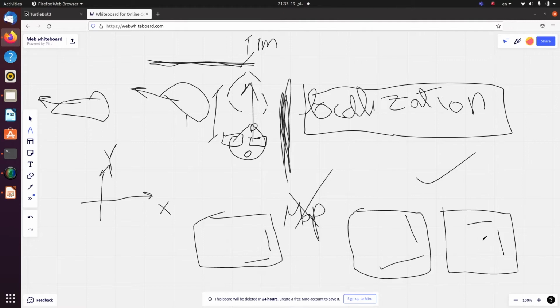So I know that the robot here was looking that way, and I know that here the robot was looking somewhere like this, a little bit rotated, and here the robot was looking here, for example, right? So by overlapping the robot locations in each of these observations, I get all of these individual local maps, and I overlap them together in order to get a very strong map where, for example, this is the robot pose after overlapping.